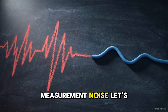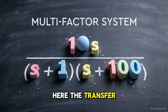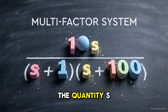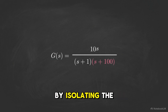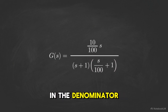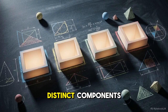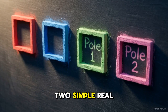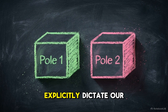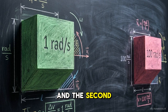Let's scale up the complexity and evaluate a multi-factor system. Here, the transfer function is 10s divided by the quantity s plus 1 times the quantity s plus 100. We immediately convert this complex equation into standard Bode form. By isolating the constant of 100 in the denominator, the math yields a clean formula ready to be broken into its base properties. We extract 4 distinct components: a negative 20 decibel gain, a 0 at the origin, and 2 simple real poles. The 2 simple poles explicitly dictate our critical break frequencies. The first acts at 1 radian per second, and the second acts at 100.